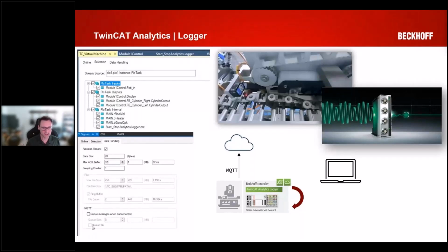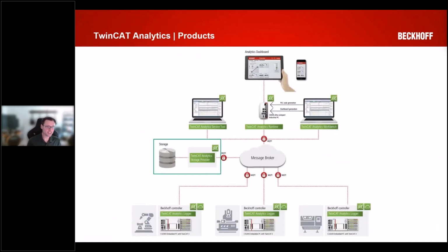And just an example of that, just sitting there and keeping a local ring buffer, like the last 24 hours of pertinent signals in your PLC. If something goes wrong, simply pull those files off, narrow in on the appropriate time frame, and take a look at all those signals and trend them, visualize them. So in that sense, it's often described as like the flight recorder or black box of your control system, which actually I learned through making this that black box is a bit of a misnomer because the thing's actually bright orange. But anyways, next comes the storage piece, and we explained sort of how this works in some depth.